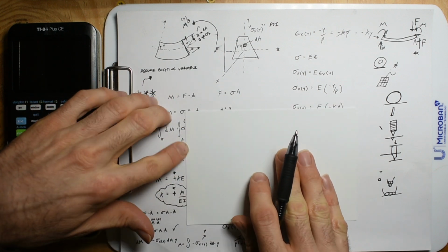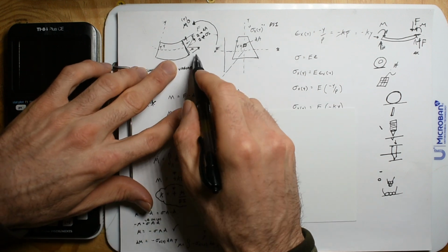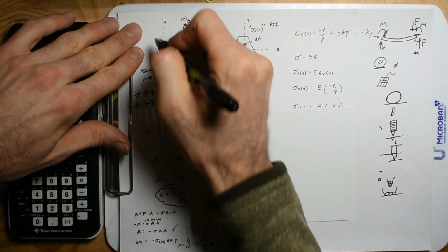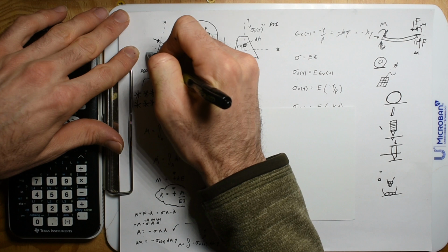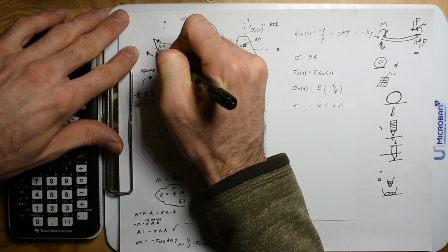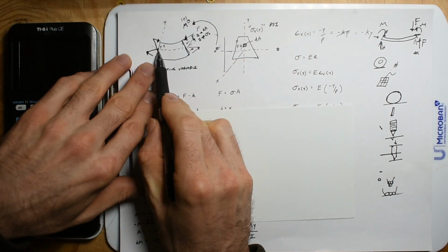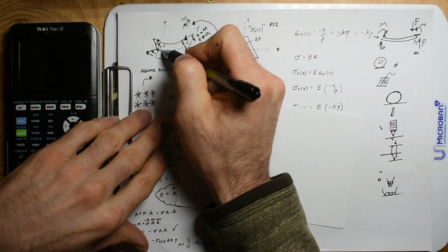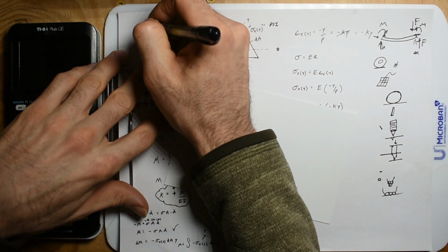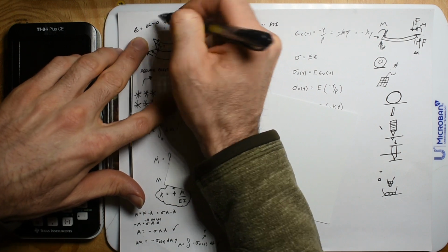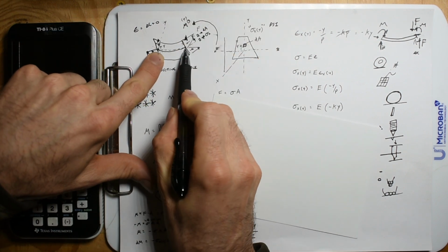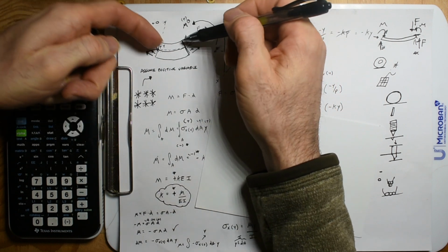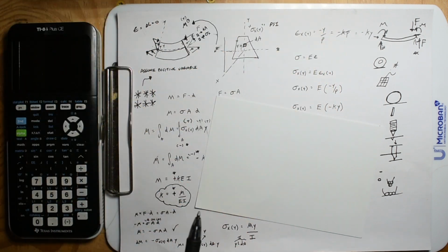And those changes in length are internal forces. So on both of these I would have a force that way and a force that way. And there is some sort of neutral axis, we talked about that, where there is no stretching. Based on the strain equation, if the change in length is 0, there is no force right here. So this is just a force diagram where we have equal forces this way, equal forces that way.